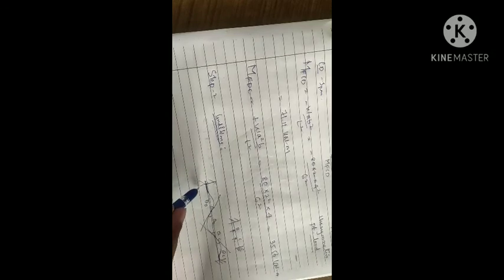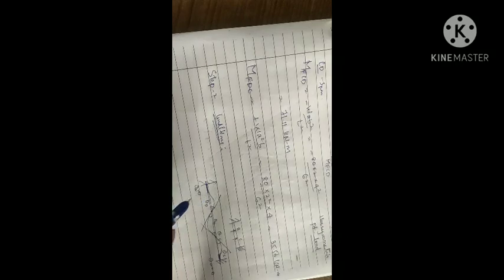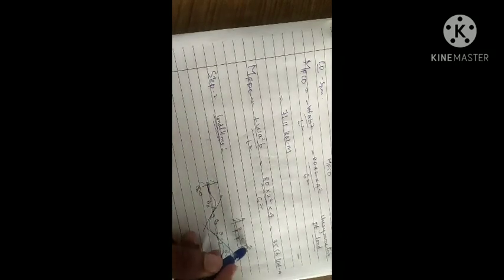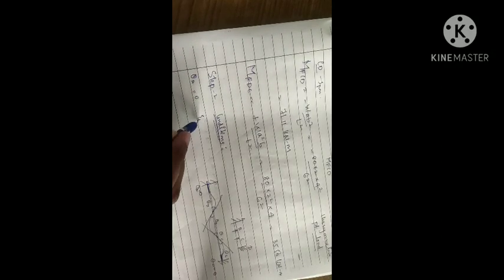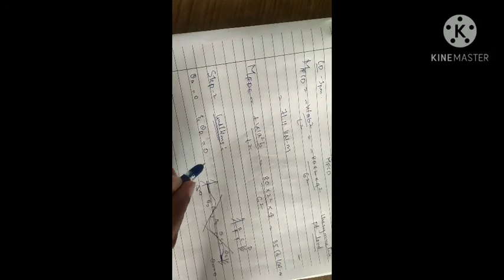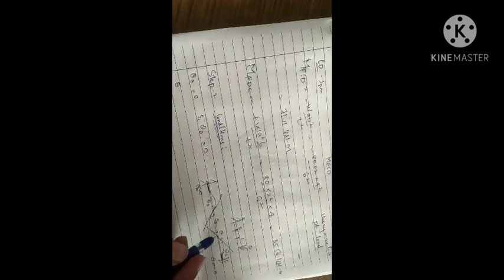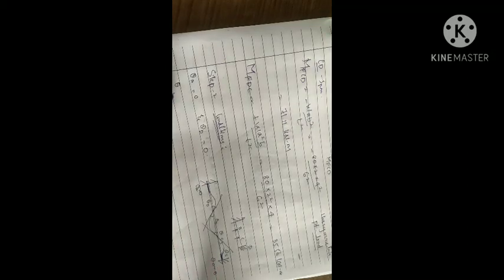You can see the flat line. A flat line indicates the angle is equal to 0. This flat line indicates theta D is equal to 0, and here it is A. Okay, A, B, C and D. Therefore theta A is equal to 0 and theta D is equal to 0. Slope development at B and C will be there, as the support is hinged and roller. For fixed end, there won't be any development of slope. So theta B and theta C exist.